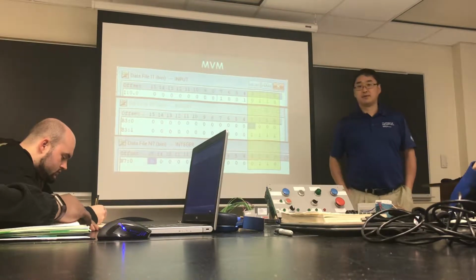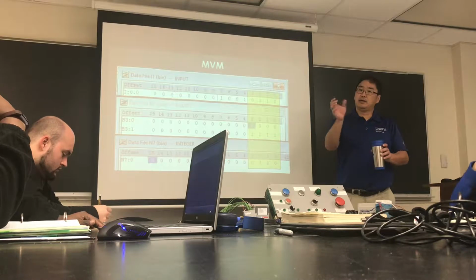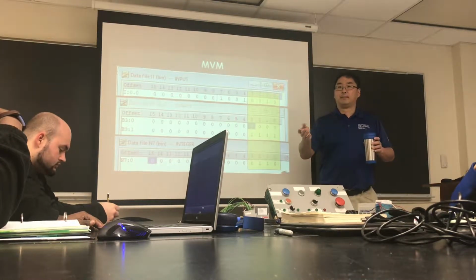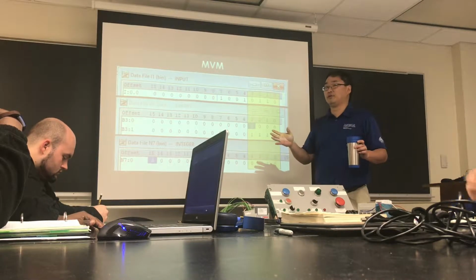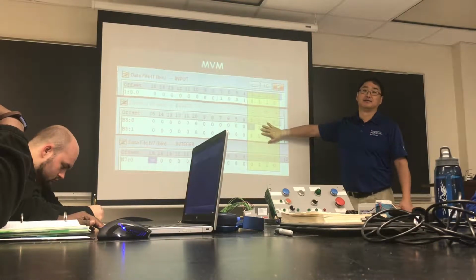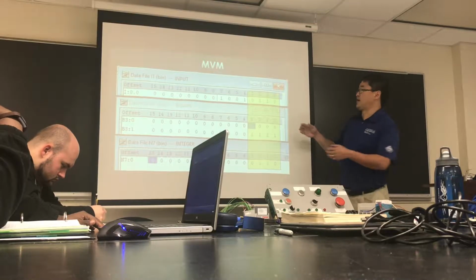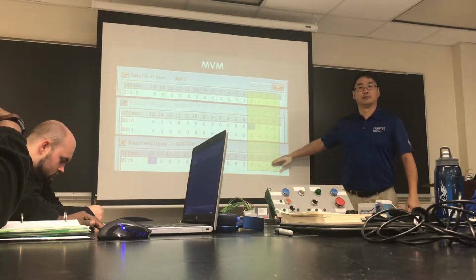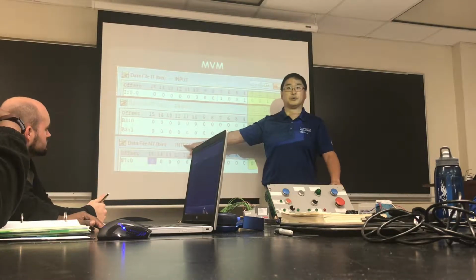Yes? What do you mean with the move? Like move what? In this case, move and copy are synonymous, can be used the same way. But there are some very, very minor differences that I don't totally understand myself. But there's only a mask move, there's not a mask copy. So when I say move it or copy it, it's take this information and move it down to here. To a different bit number? Yeah, and well, in this case, it's actually to an integer.